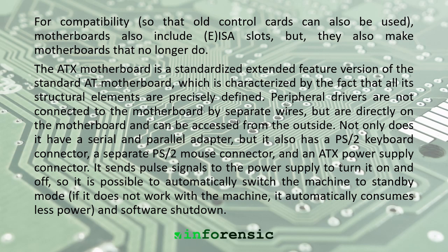The ATX motherboard is a standardized extended feature version of the standard AT motherboard, which is characterized by the fact that all its structural elements are precisely defined. Peripheral drivers are not connected to the motherboard by separate wires but are directly on the motherboard and can be accessed from the outside. Not only does it have a serial and parallel adapter, but it also has a PS2 keyboard connector, a separate PS2 mouse connector, and an ATX power supply connector.